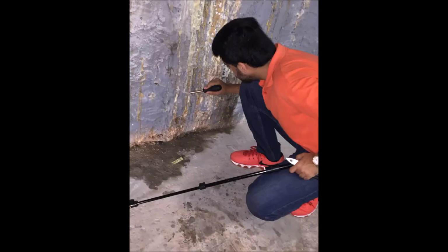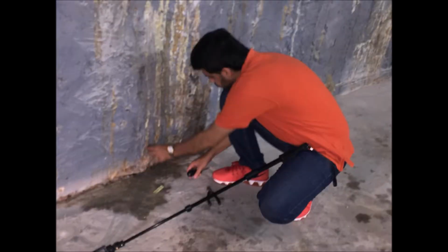Rising damp is a form of dampness that is present within the walls as a result of moisture penetration from outside or beneath the structure of property. It is a particular problem in older buildings where the damp-proof course has been damaged or when the ground level around the house or the building has been raised by the addition of a path or driveway. Also, rising damp usually affects ground floor walls across the wall's entire length and bottom part from where it can rise up to as much as 1.5 meters in height.